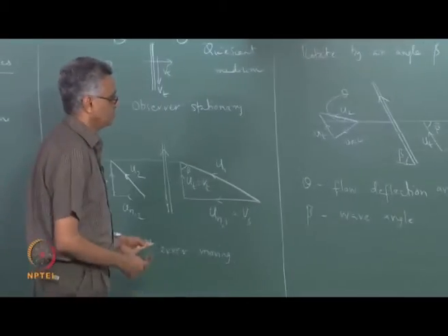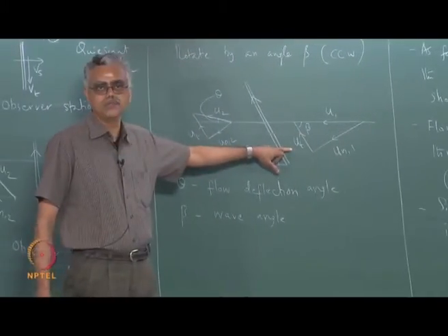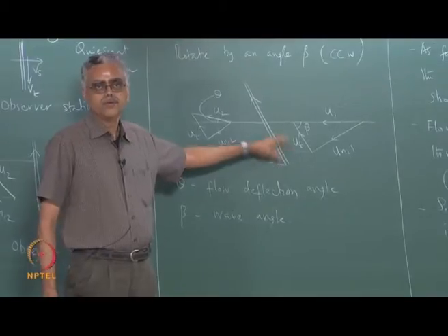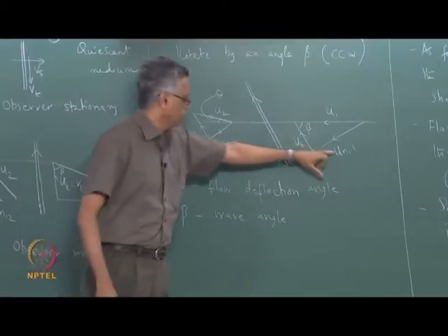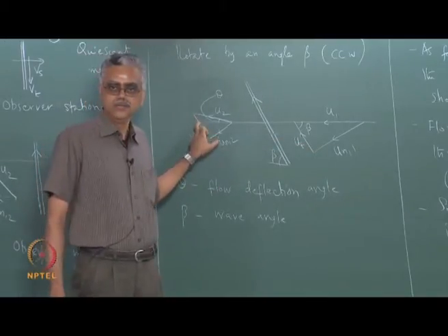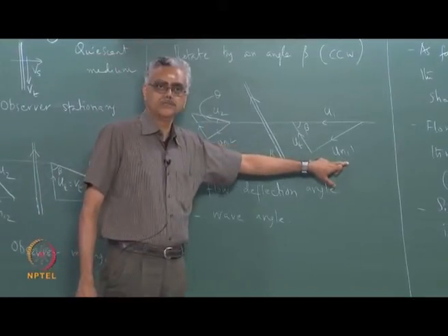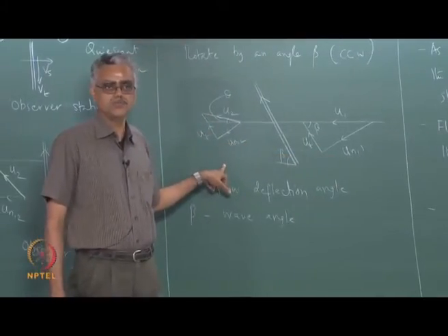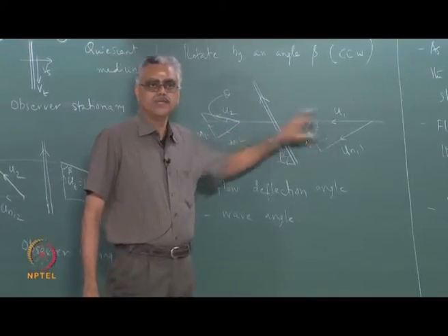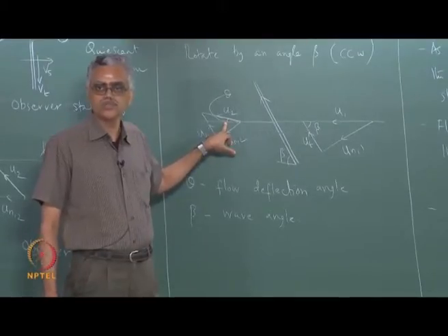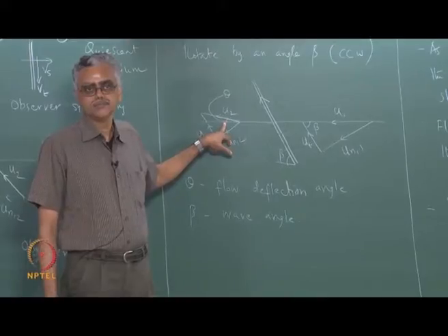Okay. Now, because the normal component of velocity alone decreases and not the tangential component, across an oblique shock wave, the flow becomes subsonic only with respect to the normal component, not the total velocity component. Mn1 is supersonic, Mn2 is always subsonic because there is a normal shock wave. However, M1 is supersonic and M2 can also be supersonic. Most of the situations M2 is also supersonic. Okay?